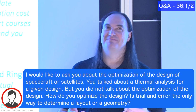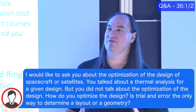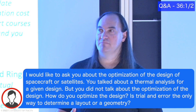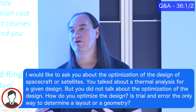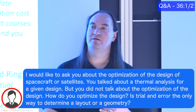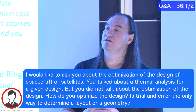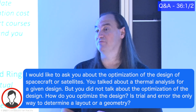Well, in a vacuum on the ground. We have to be able to interface with everybody else, and particularly the systems team needs to be the ones driving optimization. We can help constrain resources or reduce resources locally. I could use less power or do a different radiator, things like that. But how those changes flow through and have ramifications on other subsystems is very important. And you just can't optimize by yourself. It really is the system that has to be optimized, not the thermal design.